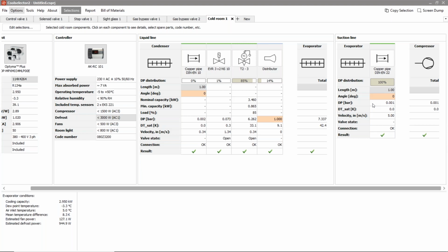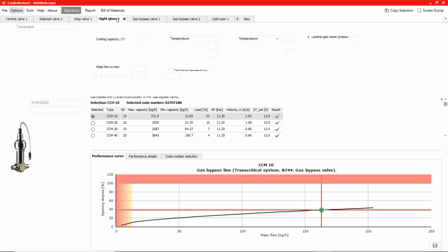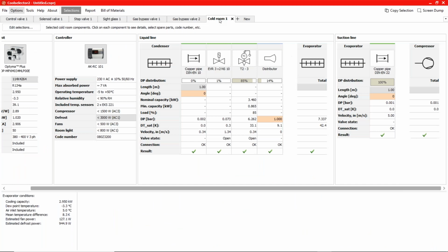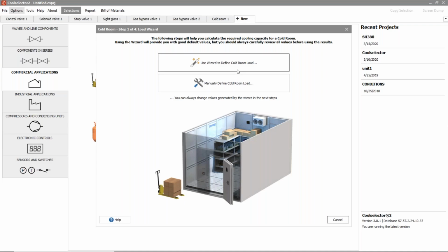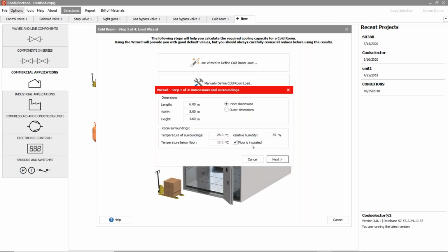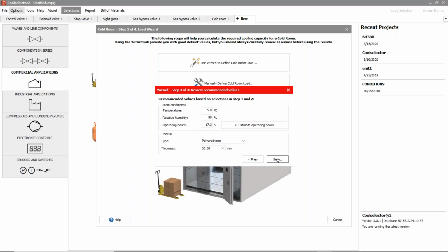So it's all about heat transmission in that case. It's the K value of the type of insulation that is going to be used in the cold room. But basically, if you go to the calculations again, we have predefined some insulation here, so you have to stick to that. Moment, let me go back to this calculation again in the cold room. So everything is predefined here. Can you see my screen?